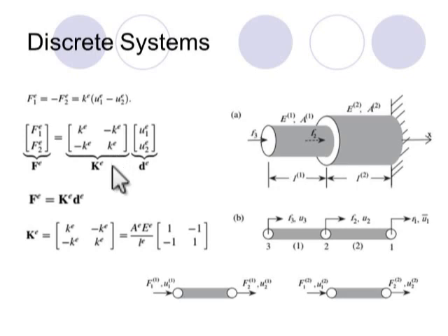As you see, the element stiffness matrix is symmetric because of the force equilibrium and the relation between the displacements and forces. Okay, so as a result, I can simply write the force displacement relation, here D is the displacement vector, as seen in this expression.